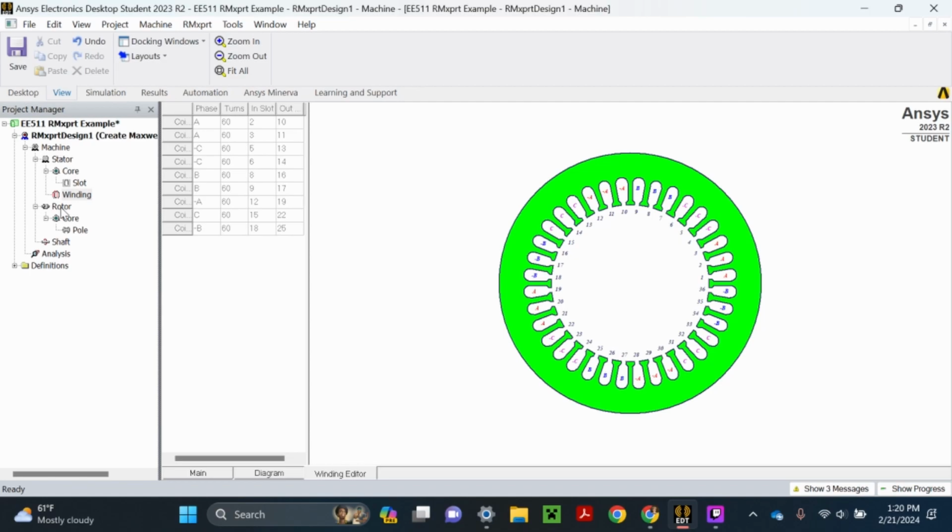I don't know, Faustin, do you have any input on stranded wire versus a solid conductor? Yes, the ohm values are different. Solid has less ohm values, but mechanically, the stranded is more flexible to make the curves. So you have to make a trade-off on what size is your motor, what's the bending, and then of course the solid makes less heat because its resistance is less.